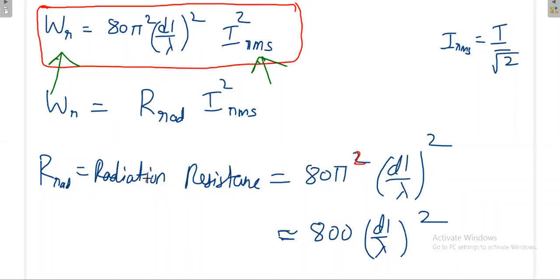Okay, then again, if you increase the length of the antenna, the radiation resistance increases, then radiated power increases. But actually that is not true, because radiated power is in your hand. Whatever power you are giving, only that the antenna will radiate. That is finally denoted by some resistance, the radiation resistance. Again, it is an imaginary resistance.